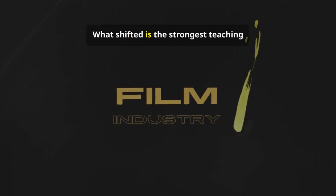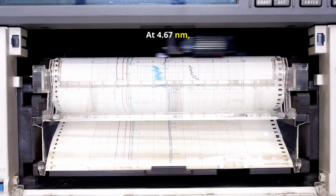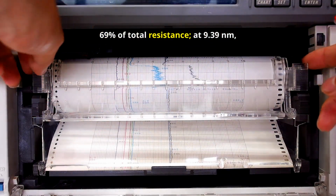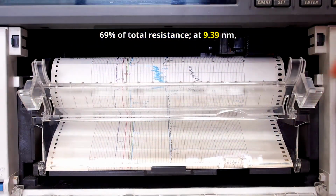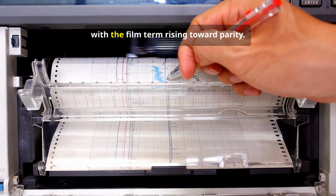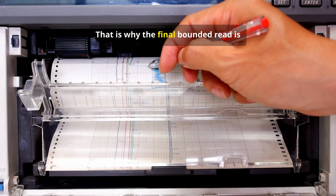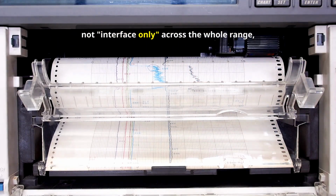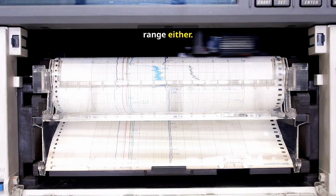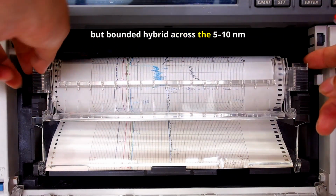What shifted is the strongest teaching point in the packet. At 4.67 nanometers, the interface term accounts for about 69% of total resistance. At 9.39 nanometers, it drops to about 52.5%, with the film term rising toward parity. That is why the final bounded read is not interface only across the whole range and not film only across the whole range either. It is interface leaning at the thinner point, but bounded hybrid across the 5 to 10 nm range overall.